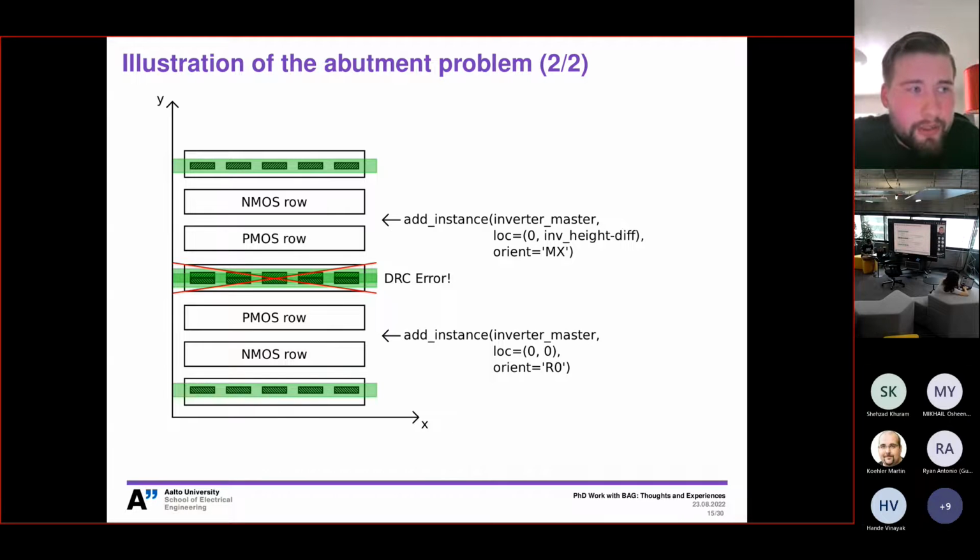Okay. But adding support would be nice. I think you can leave it out, but the problem that you mentioned with the LVS is that if you run hierarchical LVS, then you have a top level design which contains these two instances. The other one won't be clean. The layout is different.